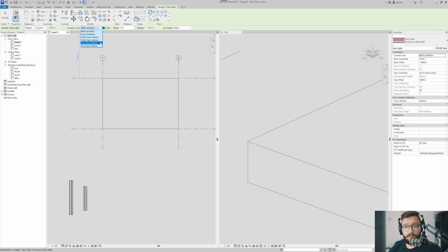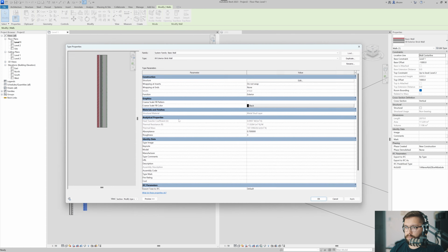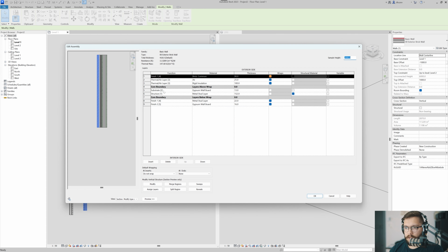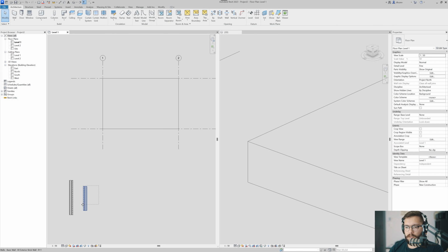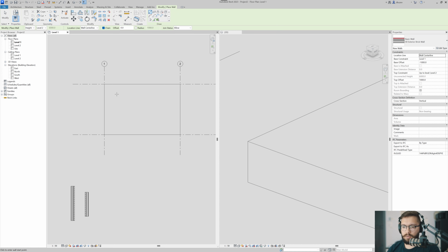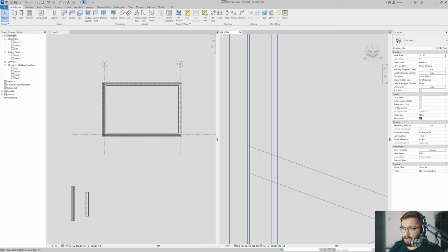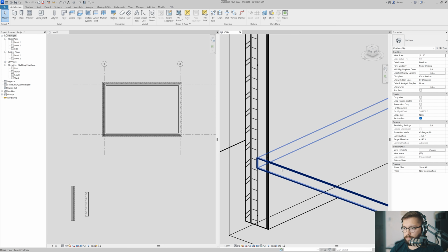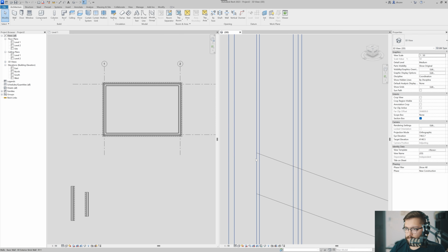So what I need to do in this case is actually align it with the exterior, because keep in mind when we created our wall, if I go to edit type, here I had my core boundary towards the exterior and the outside is right after this exterior grade gypsum board, and so on. So if I select it, I'll do WA or CS to create similar, and I would select core face exterior, and then draw my rectangle. And now you can see that it fits exactly where I needed it to be, okay?